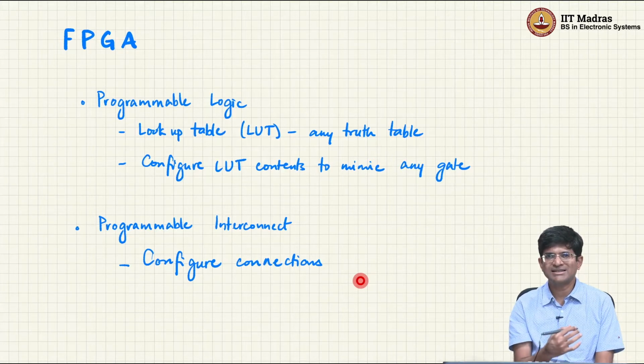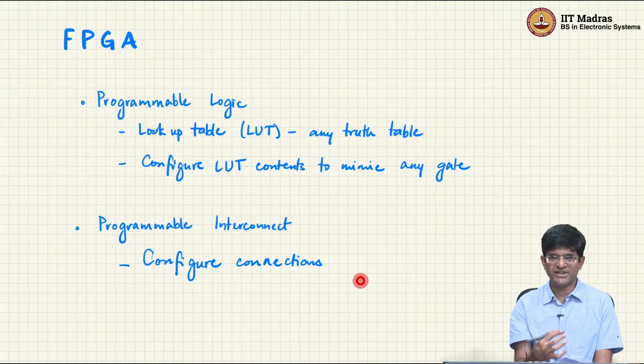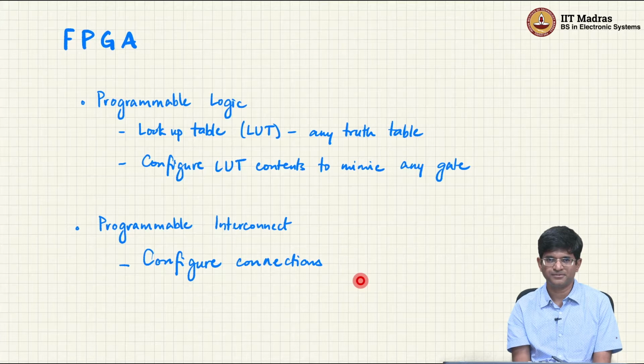The point is that's sequential. Every single Boolean equation is going to get evaluated one after the other, whereas if I had a physical set of gates that I could reconfigure or connect in different ways, I actually have the benefits of working like hardware, in the sense that the concurrency and the fact that multiple different operations happen at the same time is actually getting used, right. And at the same time I can do this in a way which can be changed later if I find that the functionality that I have got is not really what I wanted.